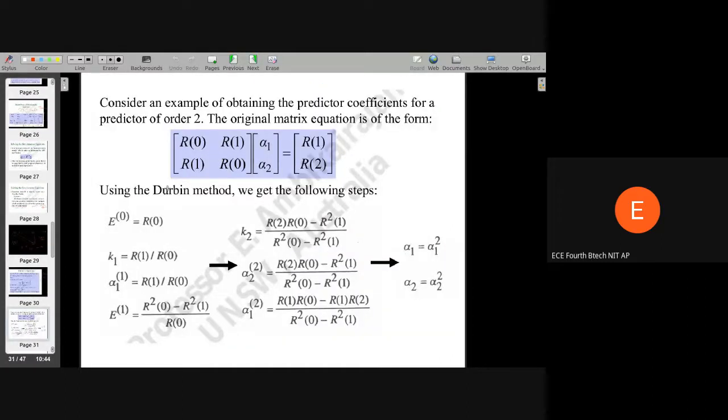Let's imagine you decided P equal to 2. Let's say there is only one resonator there. So P equal to 2, so I equal to 1 and 2. This is the structure, the Toeplitz matrix. This is the set of equations that you get, alpha I equal to 0, when you try to minimize the mean square error.